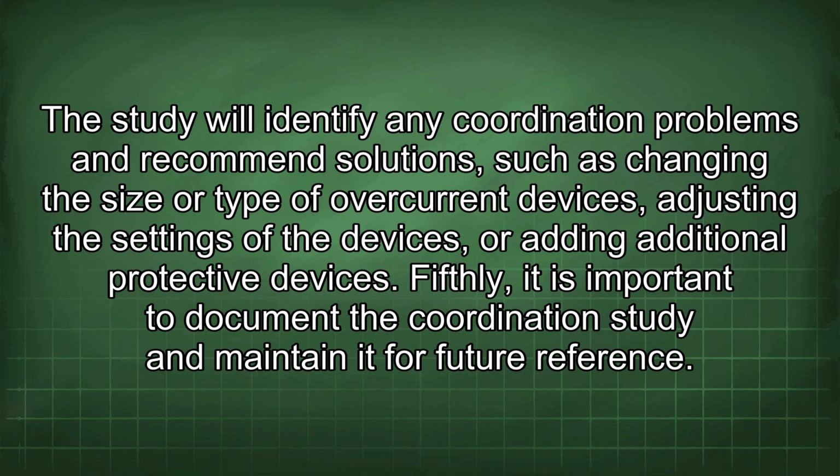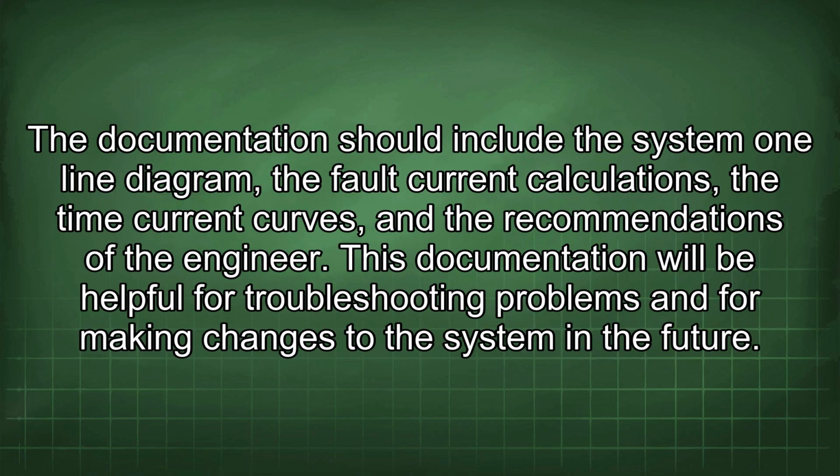Fifthly, it is important to document the coordination study and maintain it for future reference. The documentation should include the system one-line diagram, the fault current calculations, the time current curves, and the recommendations of the engineer. This documentation will be helpful for troubleshooting problems and for making changes to the system in the future.